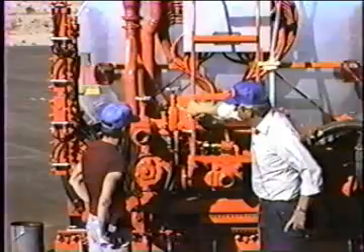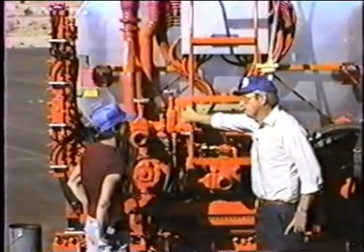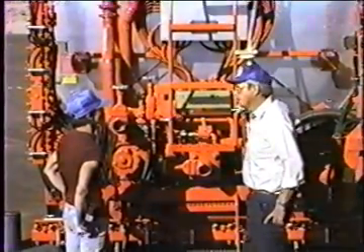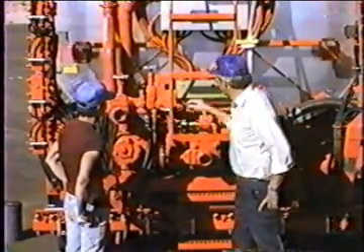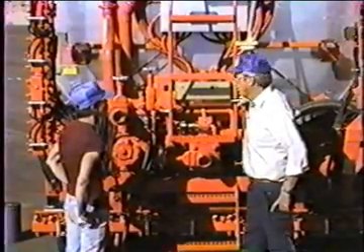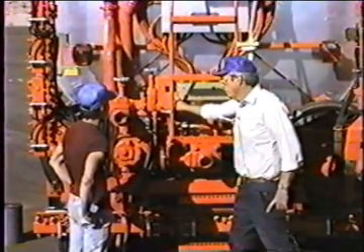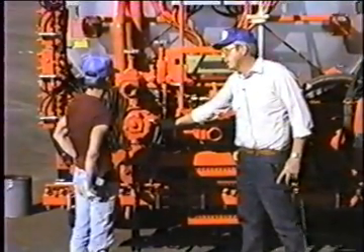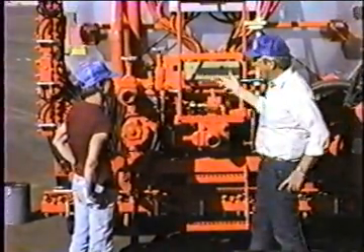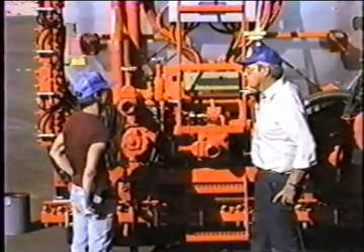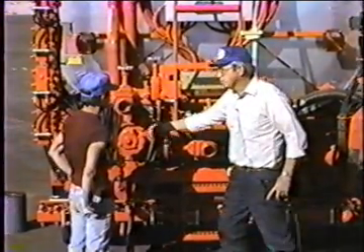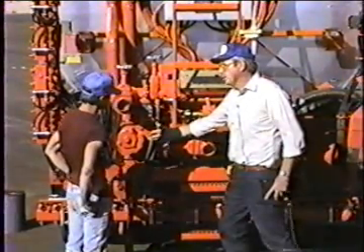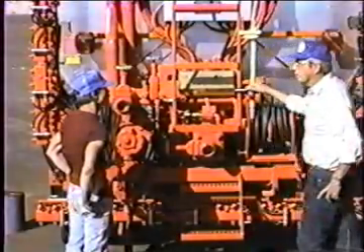Now it's fairly obvious that everything is closed. This is still closed; we haven't turned this on to do the handwork yet. This is open, but since it can't get out here, there's nowhere for the oil to go, and we've closed off the spray bar. Now, the asphalt pump has an internal relief valve that's set at about 80 pounds. So any time we're in the hand spray condition and we have closed this valve, it's just going around and around a circle within the asphalt pump itself. No harm done anywhere. It gives you good pressure to the handgun when you do turn it on.